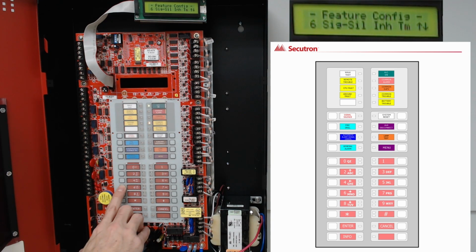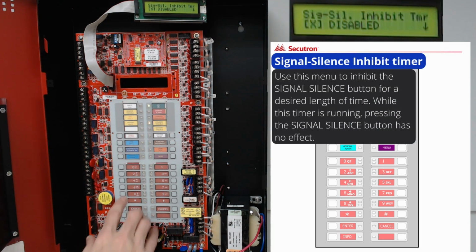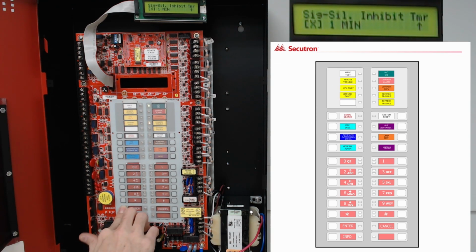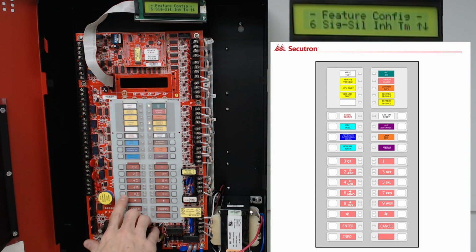The next option in Feature Config is Signal Silence Inhibit Timer. By selecting Enter, we'll enter into its options. By default, it has been disabled. By hitting the down cursor, we can see our other selectable options, which are 10-second inhibit, 20-second inhibit, 30-second inhibit, and a 1-minute inhibit. When we find the desired option that we want, we hit the left or right cursor to apply the X, select Enter, and then Cancel to exit back out to the previous menu options.